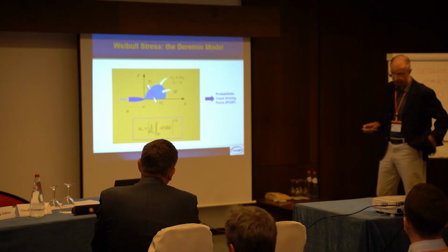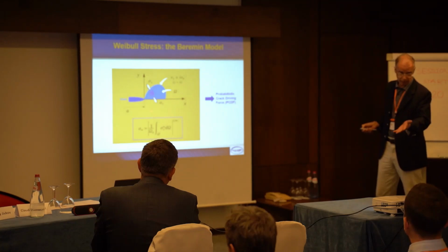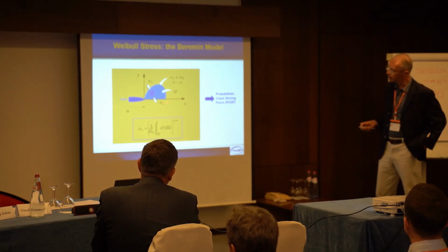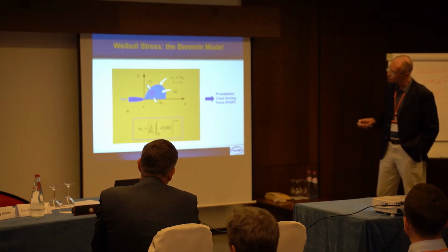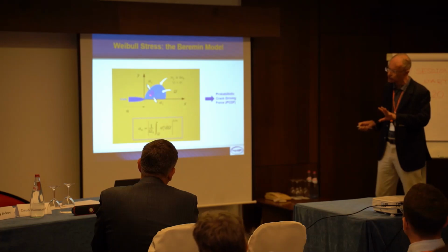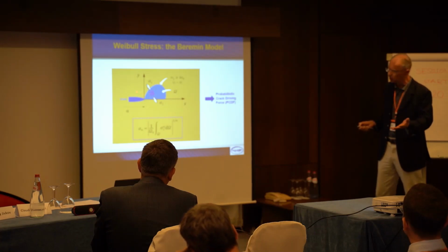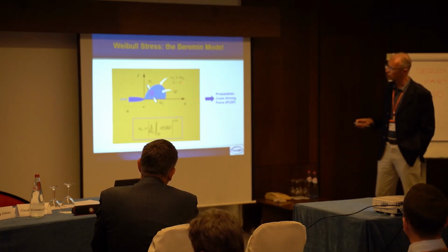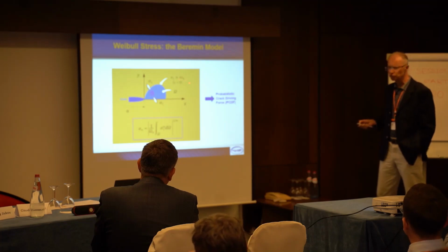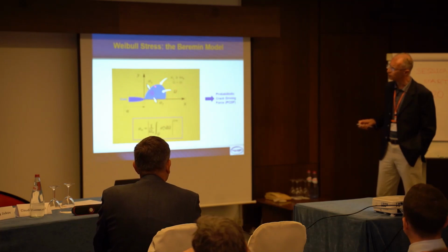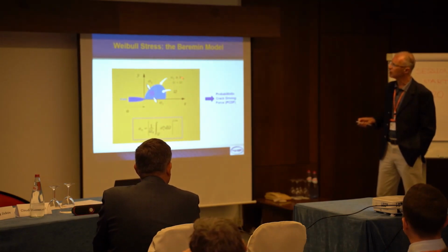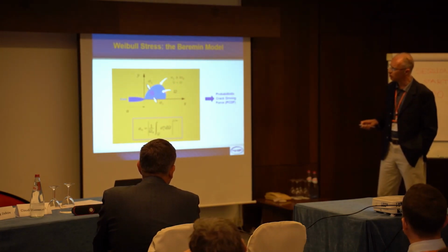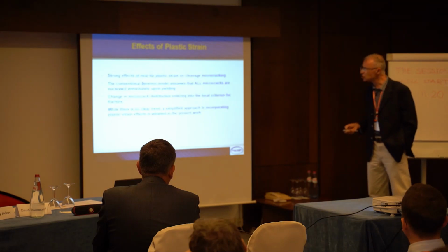So it captures first the statistical microcracks, the microcrack distribution, and it captures the actual stress distribution ahead of the crack tip, or inside the fracture process zone. This does not necessarily relate to the plastic zone. Usually the process zone is taken as the contour of 2.5 times the yield stress of the principal stresses, which defines the process zone. Okay, this is all good.